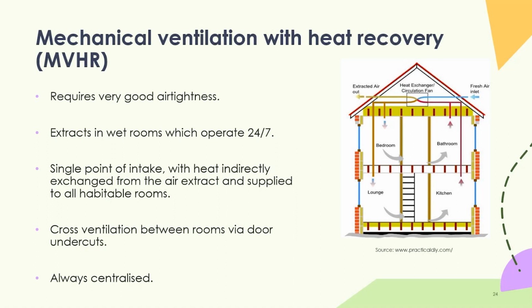That last point, it says always centralized. You can get single room MVHR units, actually, where within the one unit, say within a kitchen or within a bathroom, it's supplying fresh air as well as extracting stale air, and the air that's coming in is preheated with the warmth from the extract air.